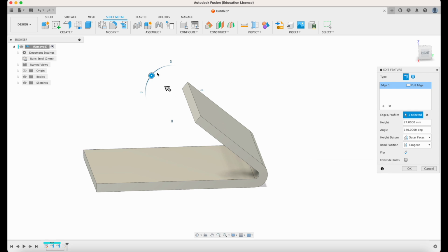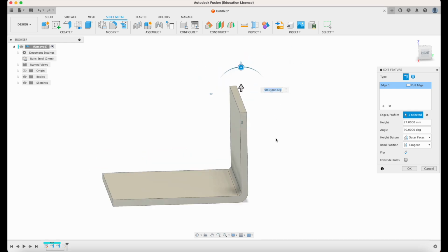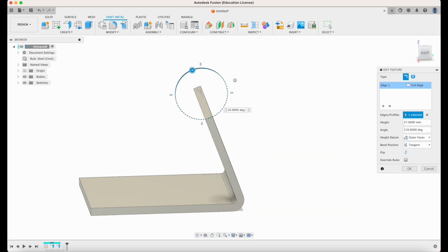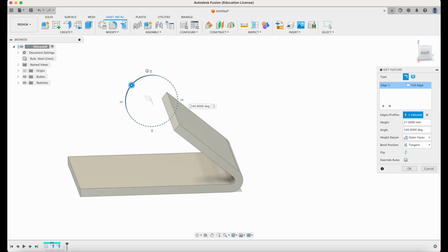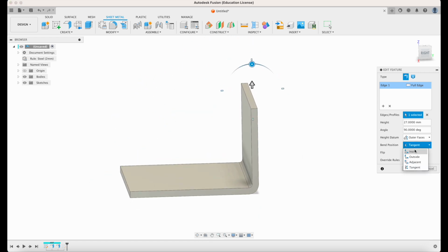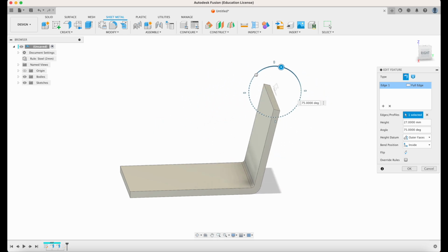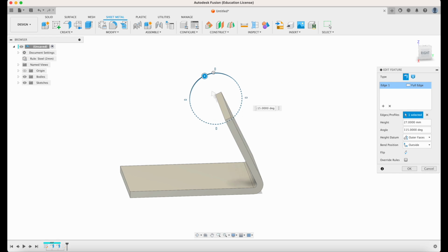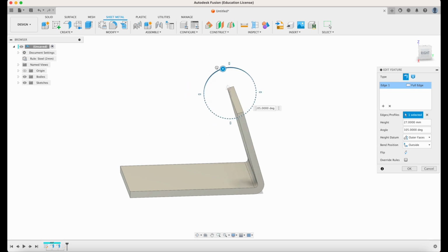As long as your bend isn't 90 degrees, okay? Now, as you can see, when you select tangency, you can't make it larger, okay? Well, in terms of angle, you can increase the angle number, but you can't open it towards the outside. If you click inside, then you can. Okay? But on the inside, if you select inside or outside, your bend will move. Okay? So you have to watch out for that.